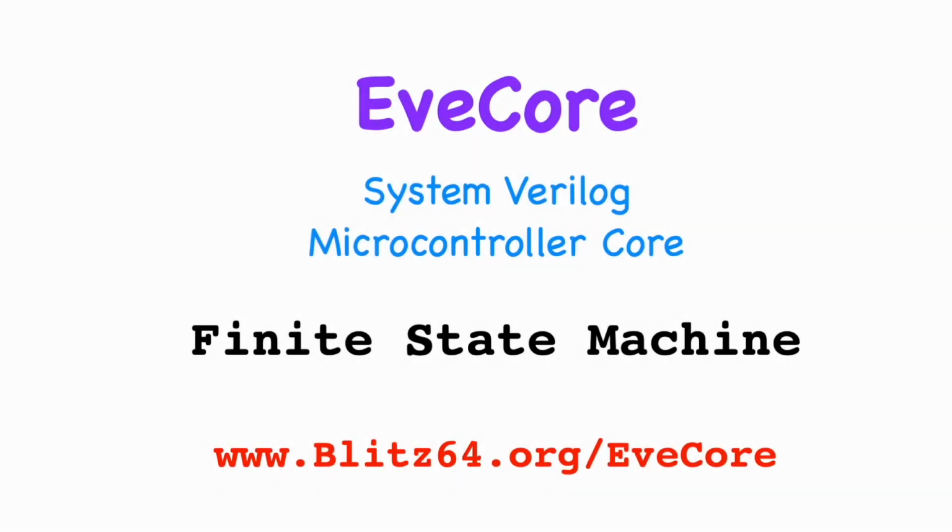This video is part of a series in which I describe how to implement a simple microcontroller core in System Verilog. In this video, I'll be walking through and explaining the System Verilog code that implements the finite state machine that controls the fetch-execute cycle. We'll see how instructions are retrieved from memory in preparation for execution, and how the finite state machine moves from state to state.